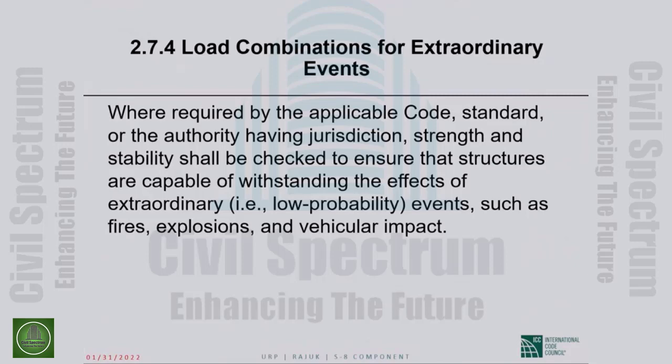So now load combinations for extraordinary events where required by the applicable code standard or by the authority having jurisdiction. Strength and stability shall be checked to ensure that structures are capable of withstanding the effects of extraordinary events such as fires, explosions, and vehicular impact.